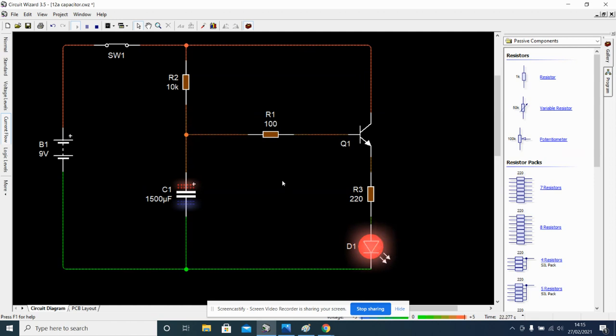Now also watch what happens when I switch the circuit off. Okay, so our LED, watch that. Still on, and then goes off. Because what's happening is the capacitor is discharging and our LED is sourcing current from our capacitor, even though our circuit is open. You might see that on cars, where there's a safety thing built in where the lights are timed to stay on to help people get into their houses when it's dark. That's one example of where you might see it.